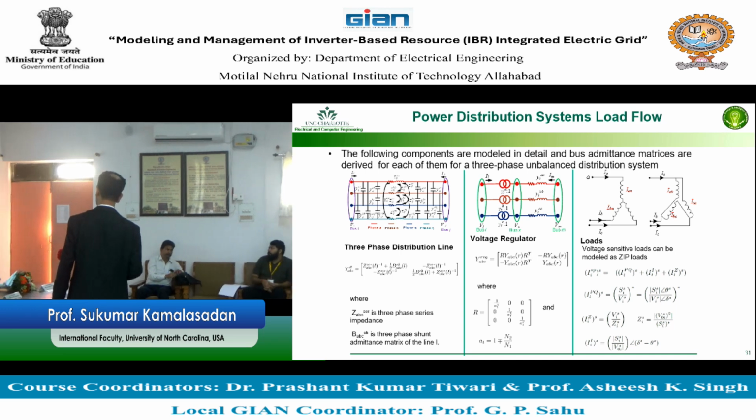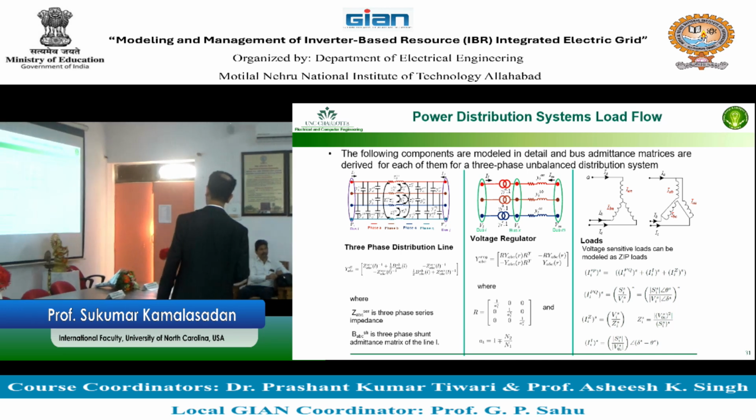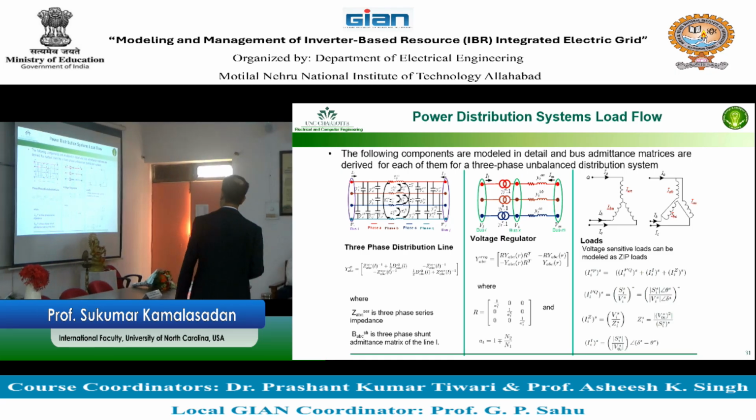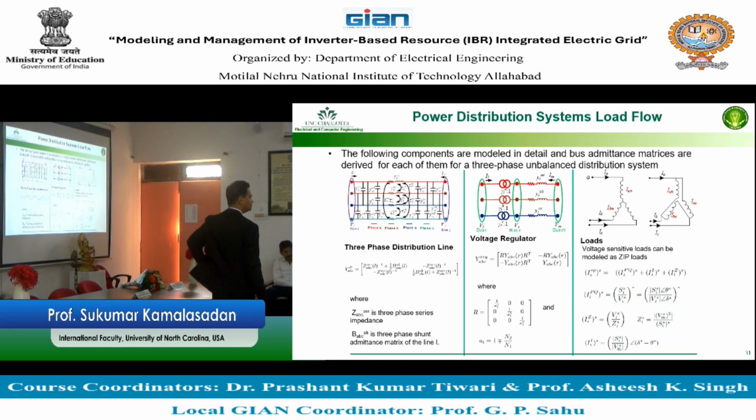One challenge is this distribution line that you are going to see has to be modeled in each phase. Remember the transmission line when we are modeling resistance, inductor. One. Why? Because all the three lines are the same, so one representation is enough. Resistance, no resistance, you ignore. Then I have inductance. That was very simple. Here you need a resistance. Can you ignore? No, resistances are there in the distribution.